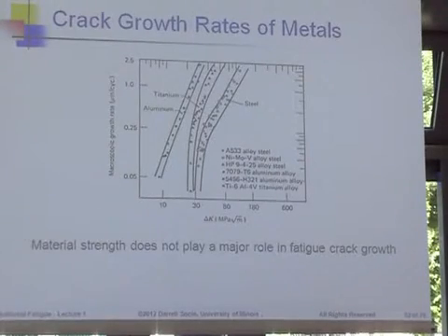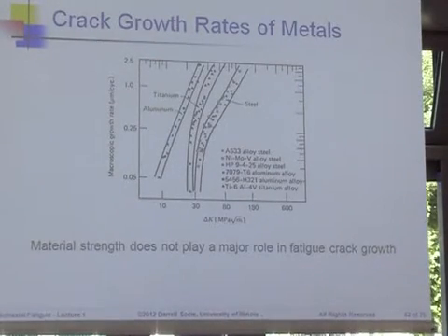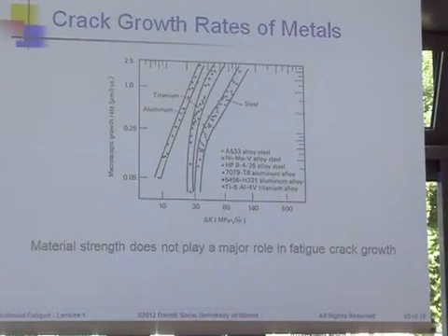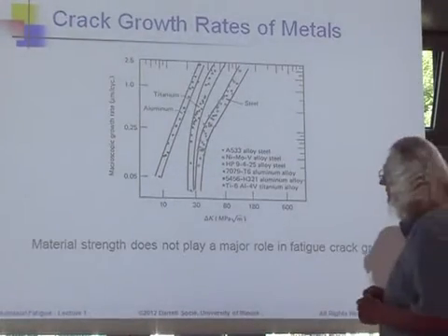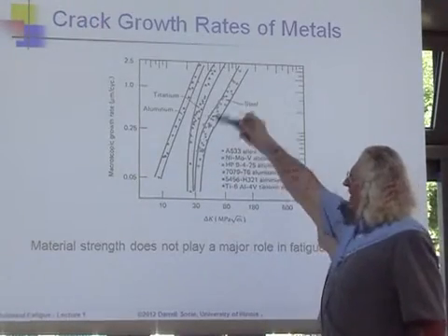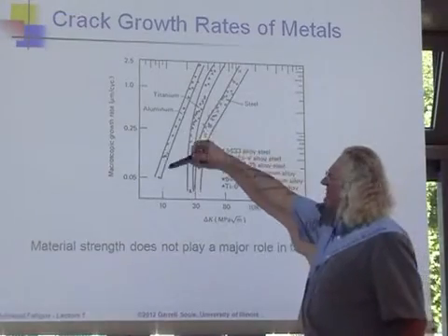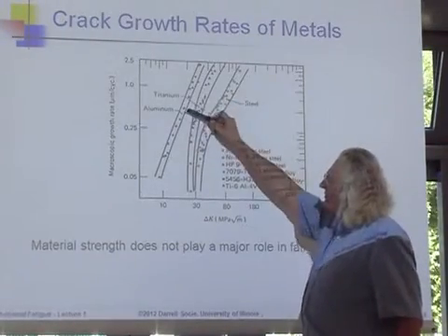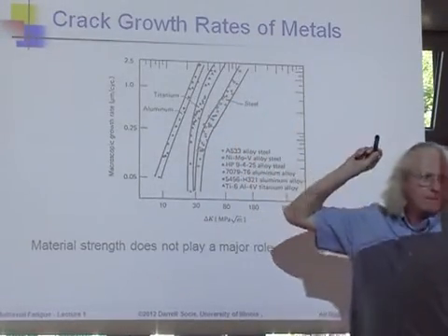So microstructure is so insensitive that, of course, you recognize this picture, growth rate on one axis, stress intensity on the other axis, that within classes of material, the crack growth rate is more or less constant. All the steels have a crack growth rate which are here. Cracks in aluminum grow 10 times faster, all else being equal.